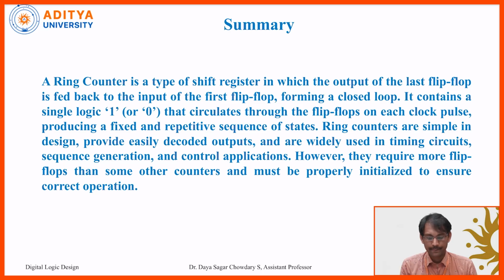Coming to the summary, a ring counter is a type of shift register in which the output of the last flip-flop is fed back to the input of the first flip-flop, forming a closed loop. It contains a single logic 1 or 0 that circulates through the flip-flops on each clock pulse, producing a fixed and repetitive sequence of states.